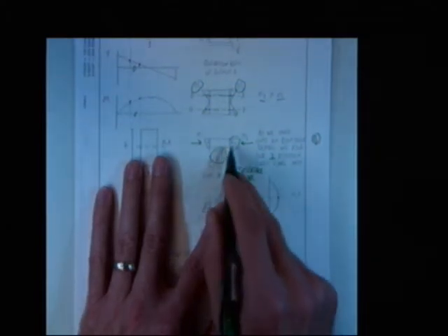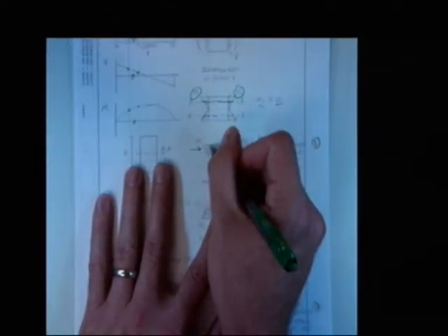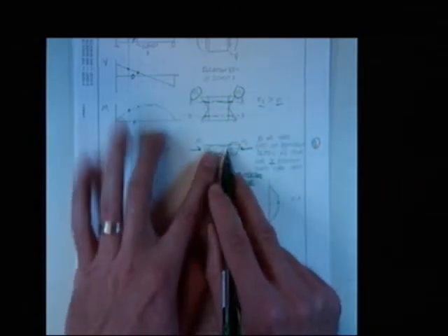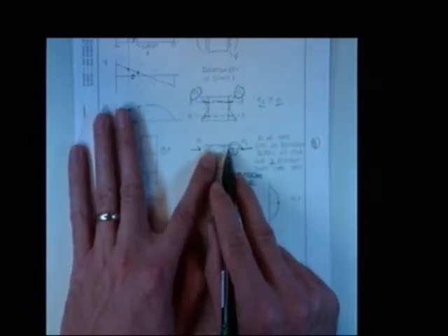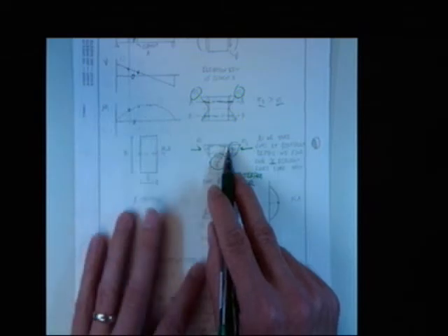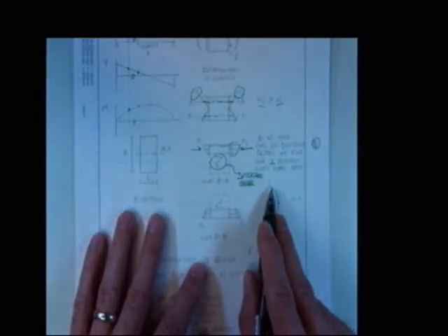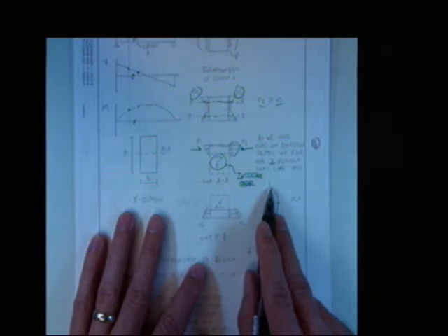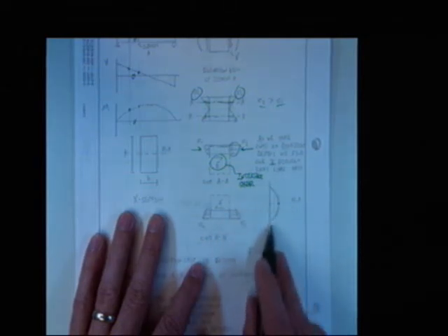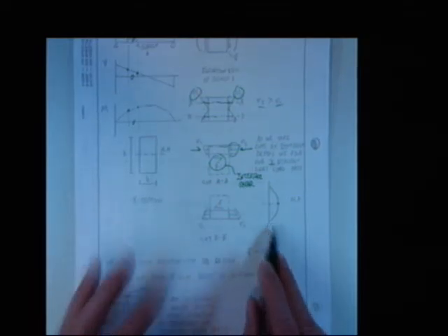At the very, very top, we take our cut right up here. There's almost no differential. Because there's almost no differential, the interface shear is zero, or almost zero. You with me? And it varies non-linearly over the depth of the cross-section. Are you okay with that? Okay, pretending to be. Thank you.